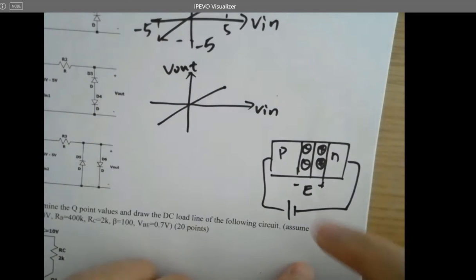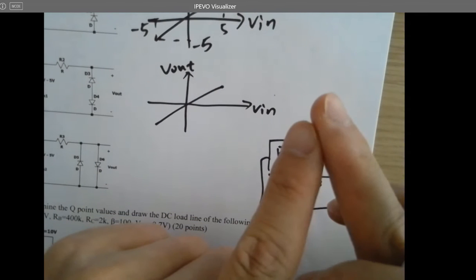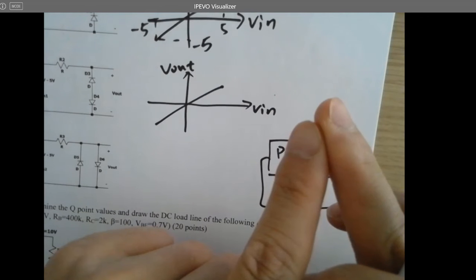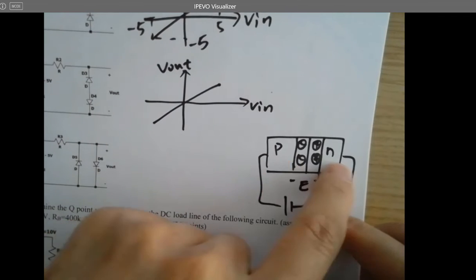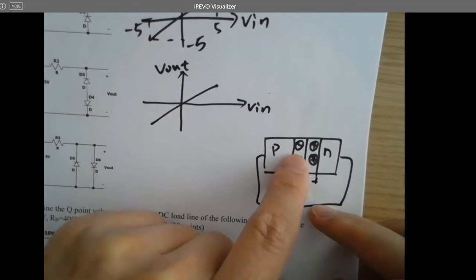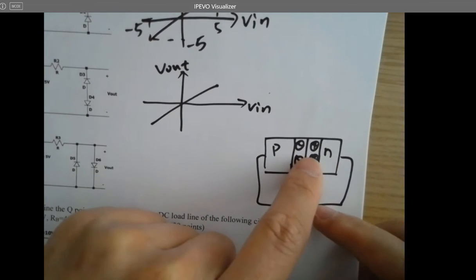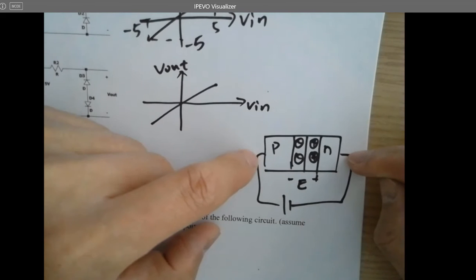So whatever the voltage is doing is to compress this depletion region, make it very thin, close to 0. So it becomes conductive. The electrons can directly tunnel through this very thin depletion region and reach here, because this is a relatively strong electric field.